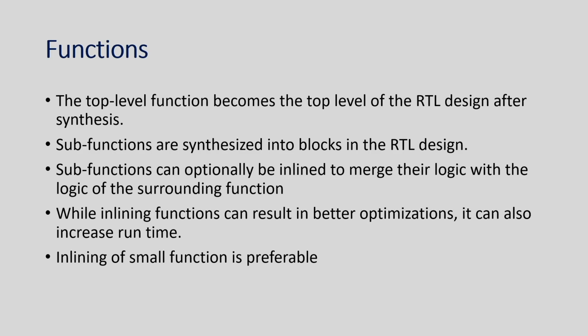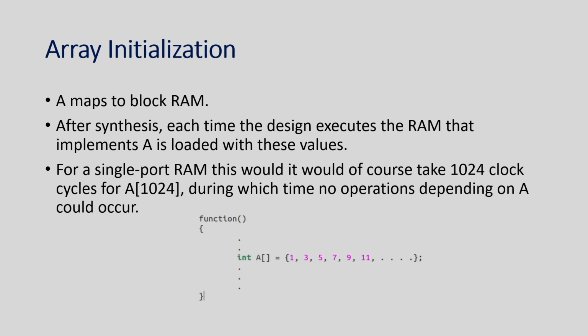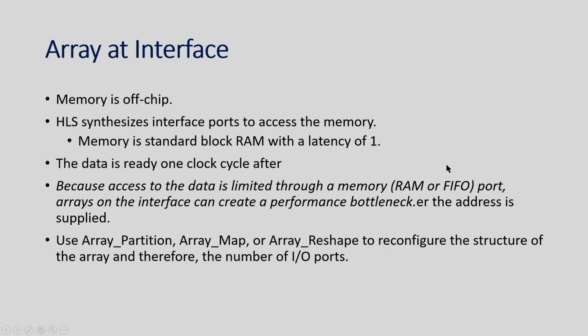We have also discussed how a function gets implemented in hardware, and specifically how resource sharing is done when functions create a separate module. We also discussed array initialization, because it creates a lot of latency if you do not take care of it properly. And we discussed keeping an array as an argument of the top level function, how it gets reflected in the hardware and how that gets managed. Those things we have already discussed in detail.